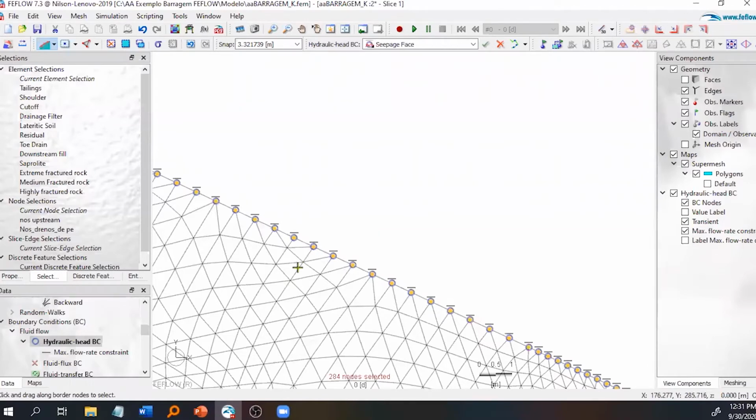It's a very nice thing of FEFLOW that you can have these constraints. So if you have a well, you could say the well is pumping at this rate, but only if the head doesn't go below, let's say, 5 meters of the pump level. And then it adds a very realistic constraint, because most of the time, if you do MODFLOW, you don't have this constraint possibility. That means that the water well will go dry if you pump more than what the system can give.